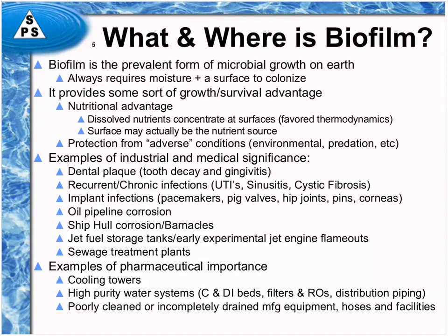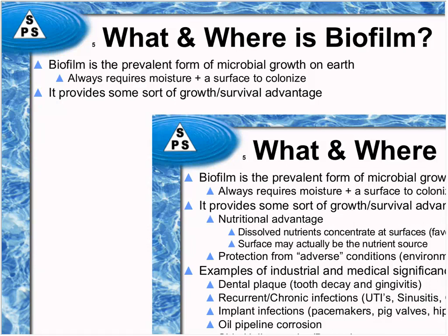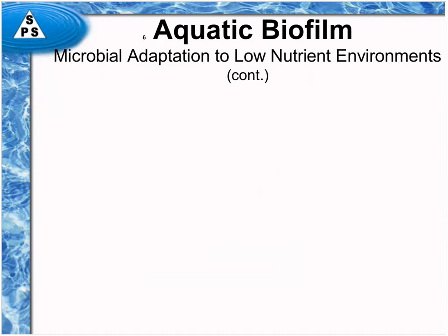Poorly cleaned or incompletely drained manufacturing equipment, hoses, and whatnot is also a source of biofilm in the pharmaceutical industry. And in many ways, these organisms growing in these areas can get into our products and then cause problems in our products. These contaminated products might exhibit poor stability or might even contain potentially pathogenic organisms that could cause patient injury or even death. So it's not like it's insignificant.